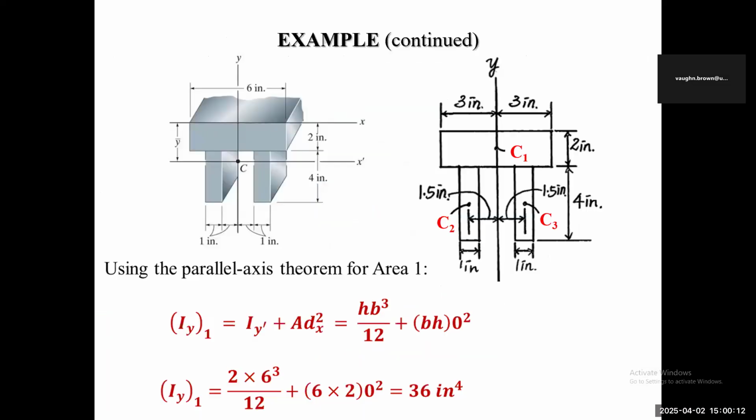All right, so now you are to find this. The first thing you do, you're going to separate the figure into regular standard shapes. So far, these are rectangles. So you have rectangle 1, rectangle 2, rectangle 3. Are you seeing it clearly? Now, the first rectangle, what's the dimension of the first rectangle? The length is 6 and the height is 2. So that means the area is 6 times 2, which is 12. So we know the area for that.